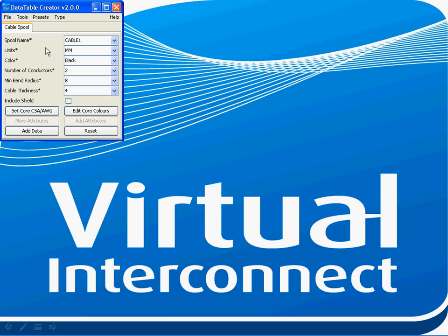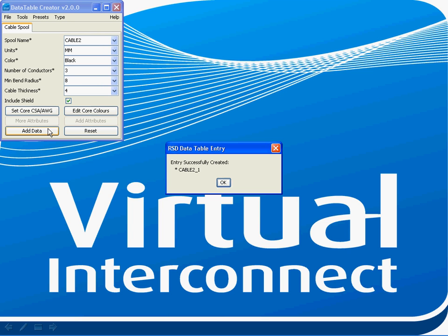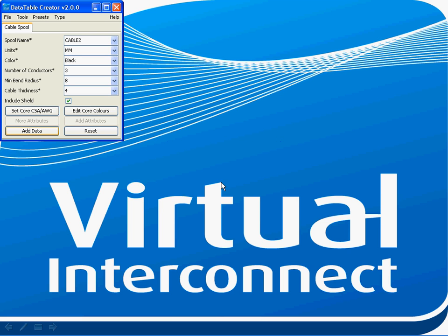Having created a line in this data table to represent the unshielded cable, I'm now going to create another to represent a shielded version. I start by giving it a unique spool name. RSD counts shields in the total number of conductors, so I need to increase that by 1, and then click Include Shield. All of the other values that I've set, including the wire gauge and the core colors, are already there, so all I have to do now is click Add Data to complete the data table.